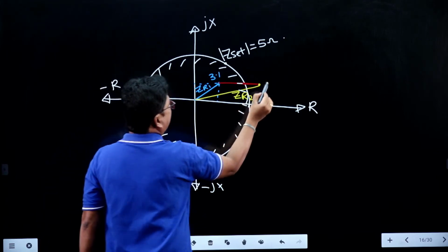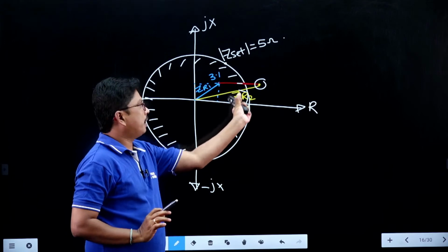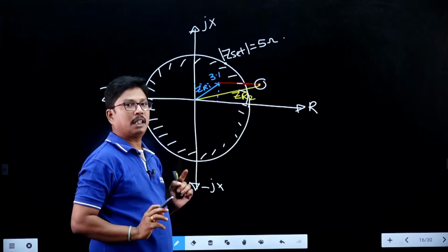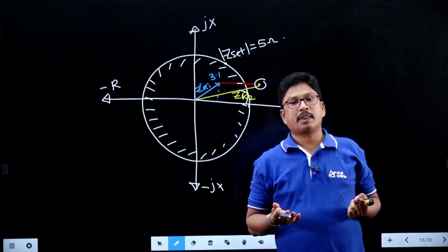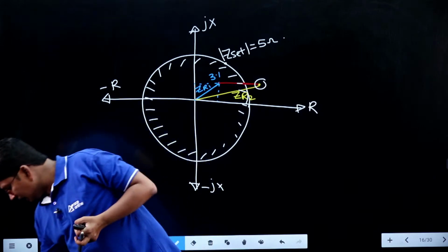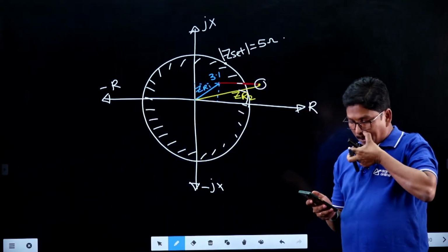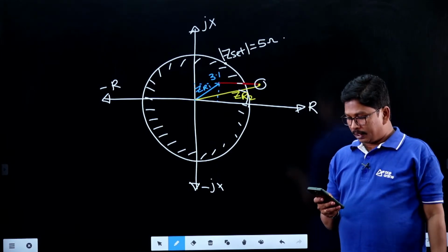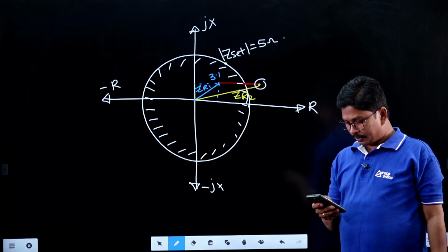And where you have the fault point, so this is the point now, right? Not the fault point, the impedance point. This is the impedance point and it is more than Z set, so the relay fails to operate. That is called the underreach problem. Is it clear, everybody? Durga Prasad, are you there? That is called the underreach problem, right?